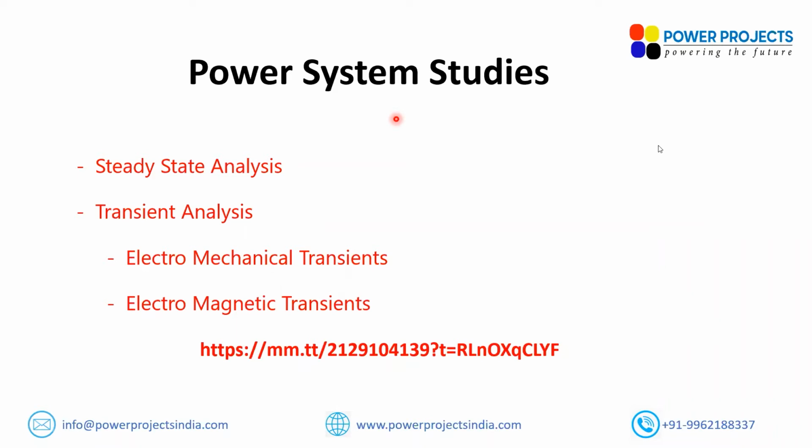This is more specifically applicable where you want to study the system with a time step of a few milliseconds. For example, there is a three-phase voltage fault in a 400 kV system, the fault lasts for maybe 100 milliseconds, and you are trying to study the relative angle of various generators for 10 seconds or 20 seconds.